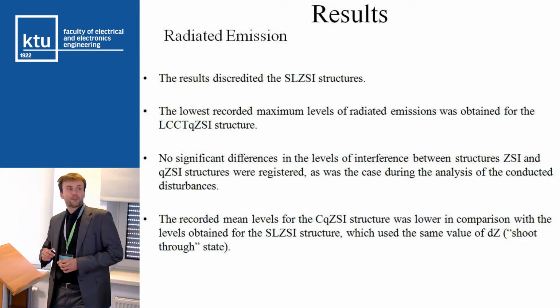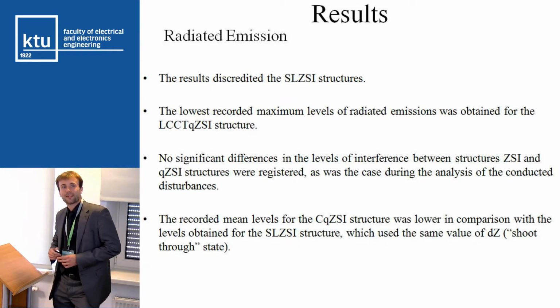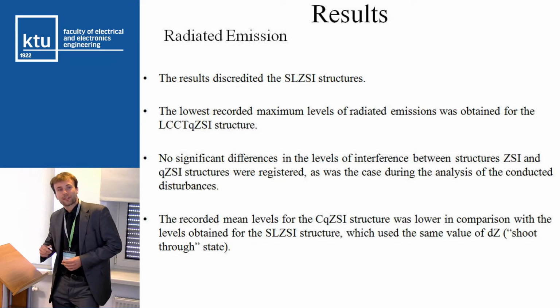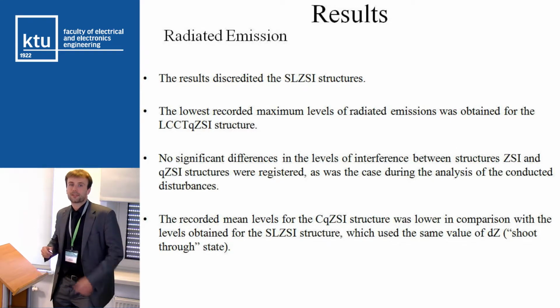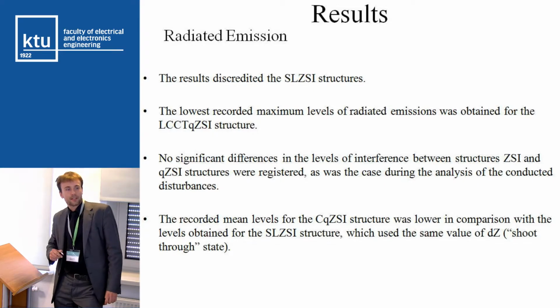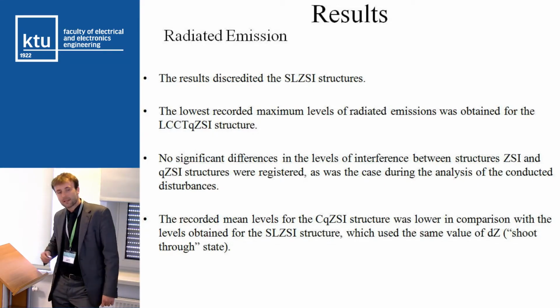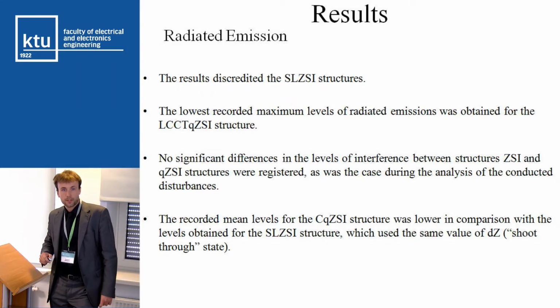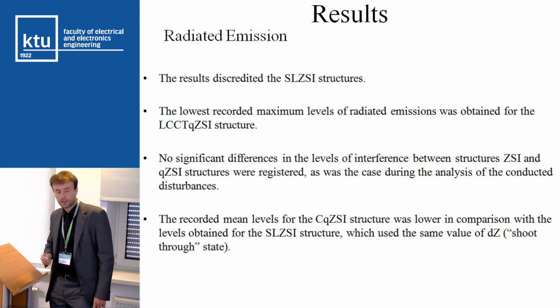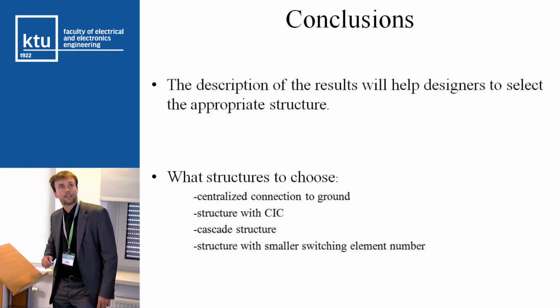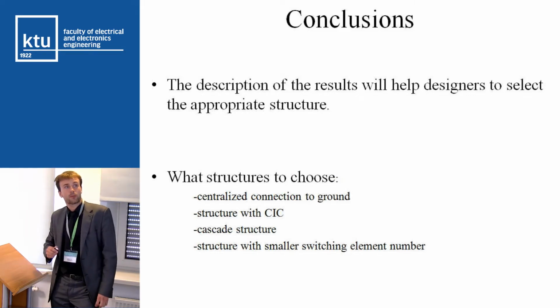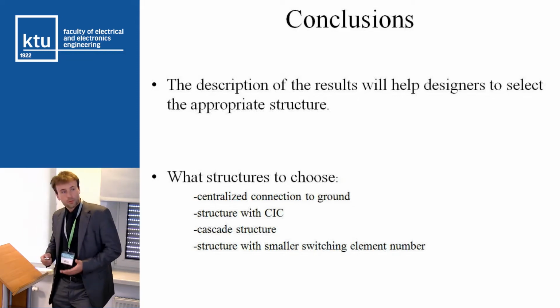No significant difference in the levels of interference was registered between the Z source inverter and quasi-Z source structures, as we saw in the conducted disturbance analysis. The recorded mean level of the quasi-Z source structure was lower in comparison with the level obtained for the switched inductance structure.